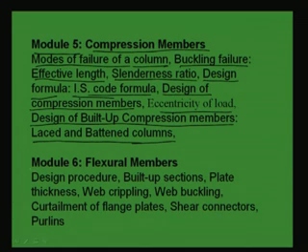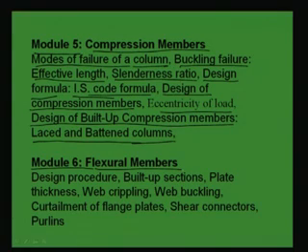In module 6, we will discuss flexural members. Flexural members means beams, that is, where flexural action comes into picture. As we know, when a member is under transverse load, bending moment will develop, right. So, because of bending moment, bending stress will develop. How to design against this bending stress, that we have to see. The member in which this bending stress is developing is generally called a beam member, or flexural member, right.